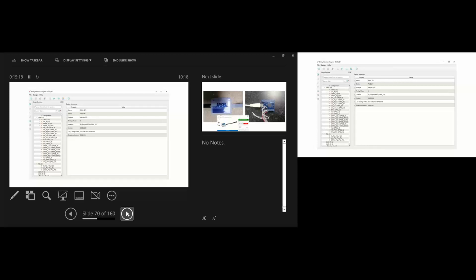Well, for a while, I quite liked it. But then I started to come across other issues. Their PLLs only have 3 outputs. That's a little bit awkward. We had to cascade PLLs, some jitter issues, etc. You can't reprogram the PLLs, which you can with the Altera devices. So that's a feature that we were using. So we have to find ways around, and yeah, just keep in mind that stock list and those part prices. Next slide, please.